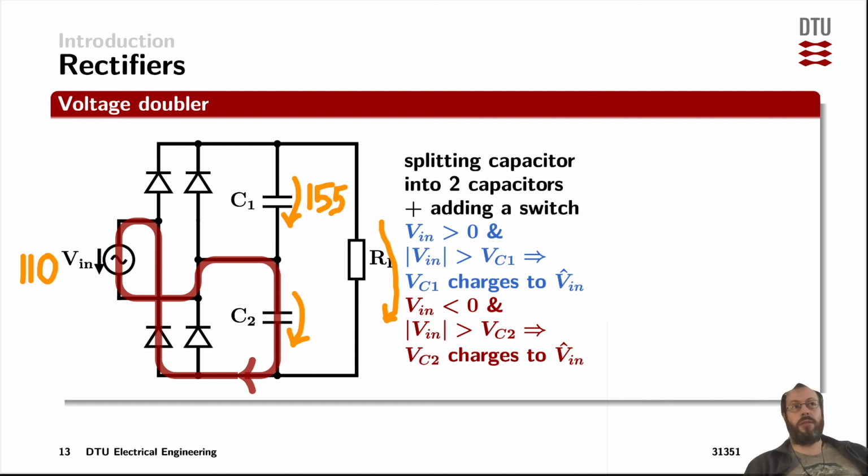If we open that switch here, then we get the European mains voltage, and the European mains voltage is closer to that same voltage again. So everything downstream here would need to operate at the same voltage in Europe as it would be operating in the US. In Europe, it would have 325 volts at the output here, if that switch would be opened over here.